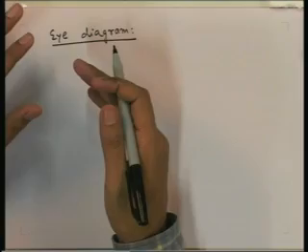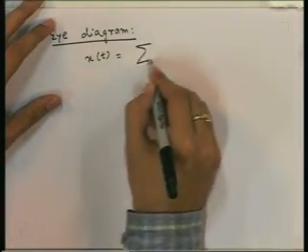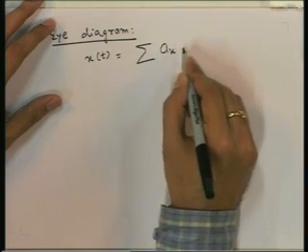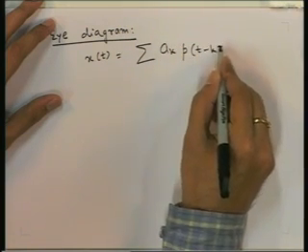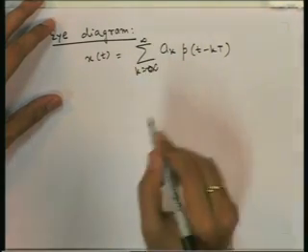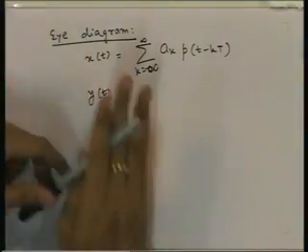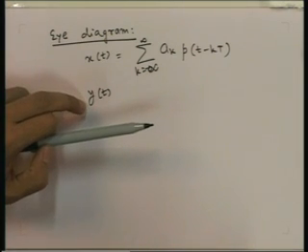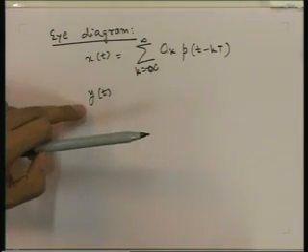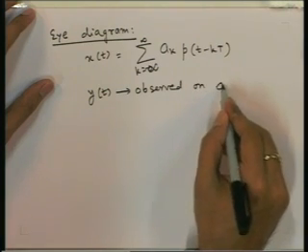So, we will have some transmitted signal x(t). This is the summation of a_k p(t minus kT), k equal to minus infinity to infinity, and then we will have y(t), which is the output of the receive filter, and then we will observe that output on an oscilloscope.